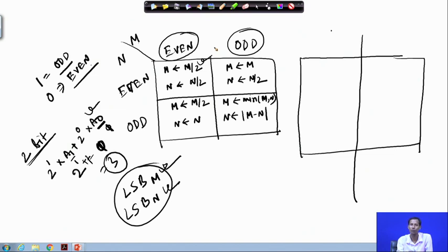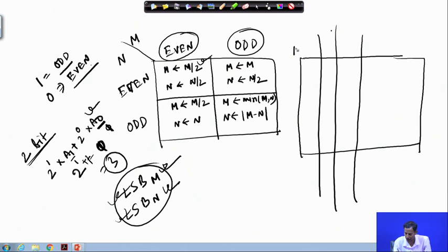This will indicate whether m is even or m is odd. So, we will find out based on these two functions of LSB of m and n. This will be the control signal which will produce the corresponding functionality changes in each cycle. So, I require this initial signal, LSB of m and LSB of n.